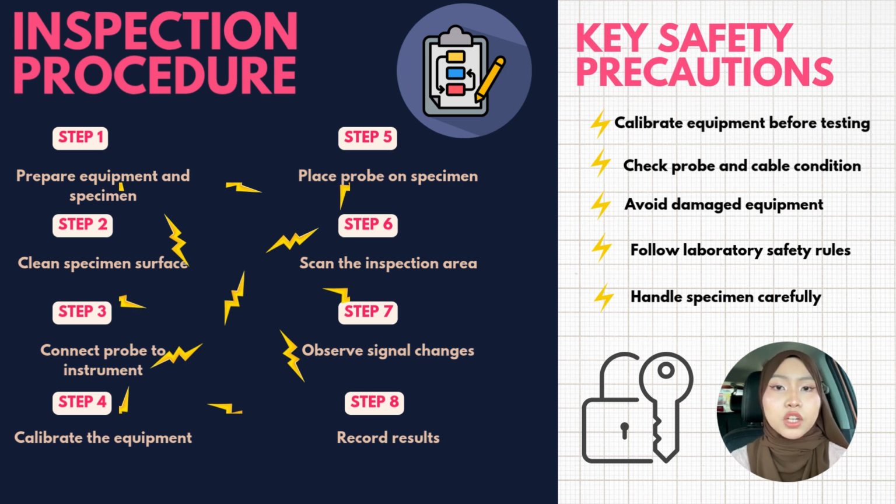Always calibrate the equipment before testing. Check that the probe and cables are in good condition. Avoid using damaged equipment, then follow the laboratory safety rules and handle the specimen carefully. If you follow these steps, it will help ensure accurate inspection and safe operations.